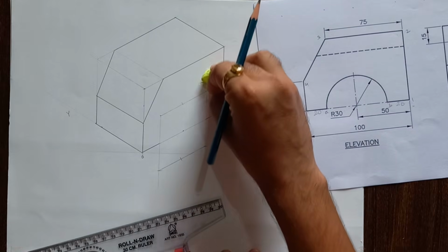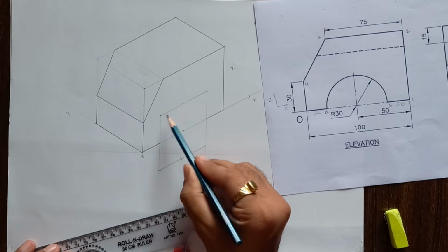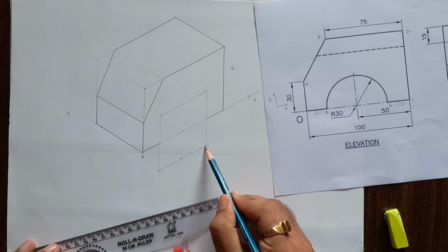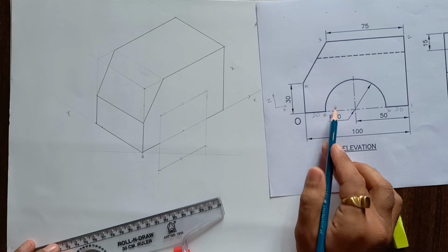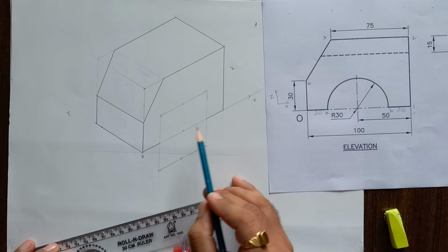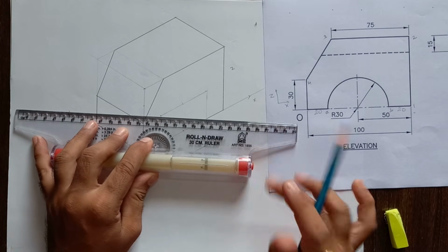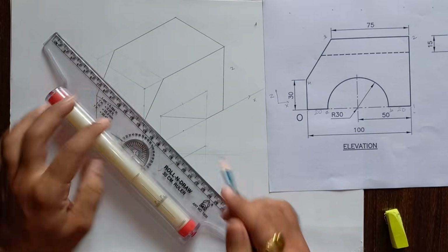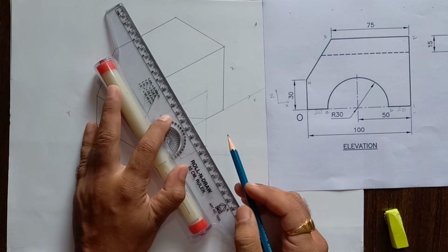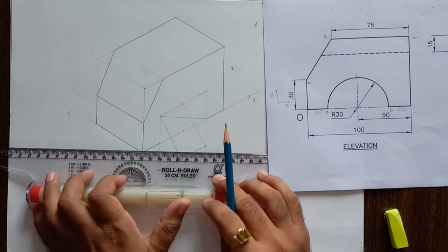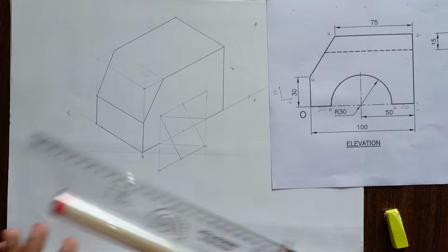In this rhombus we have to make the half circle. Now for this rhombus, these two angles are the obtuse angles, so we will draw this circle by the four center method. For that we have to join the obtuse angle and the midpoints of their opposite sides. So join the obtuse angle and opposite side midpoints by using thin lines.